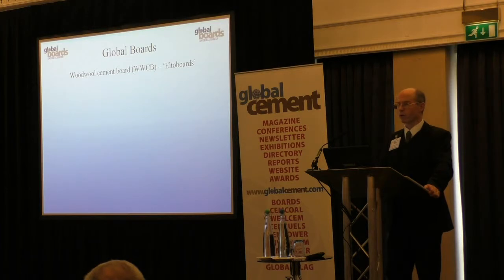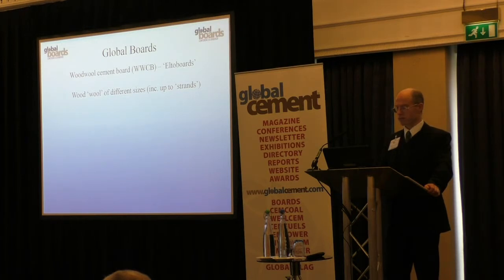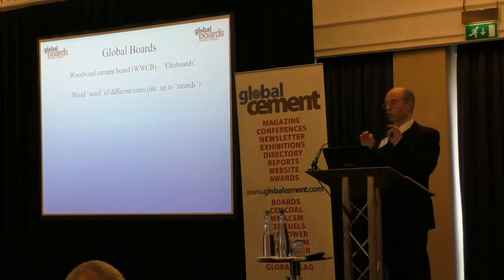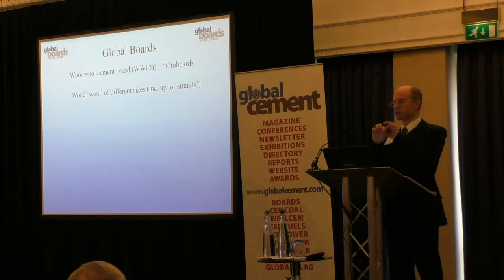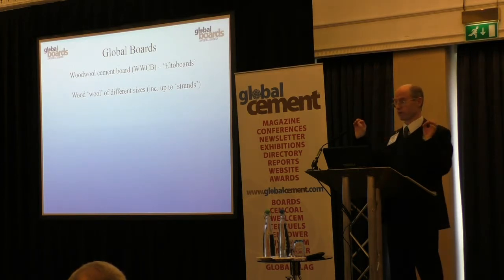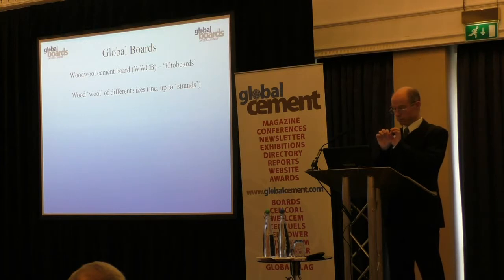One step up, if you like, from these in terms of sophistication would be wood wool cement boards, WWCB. You will often see that acronym, also known as Alto boards, and that's a Dutch company that's successfully exported its technology to a number of companies around the world. This incorporates a wood wool, which essentially is composed of longer strands of wood of various different coarsenesses that can be very, very fine, or they actually can be rather coarse, including up to what they would call strands, which would be several millimetres across.